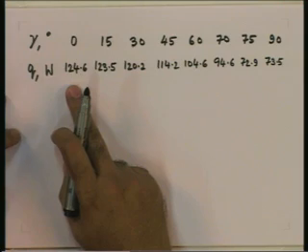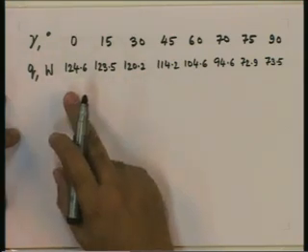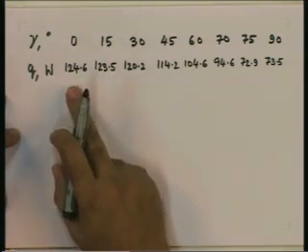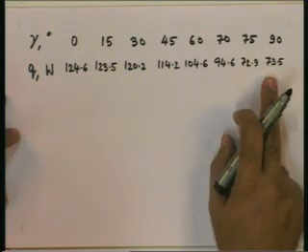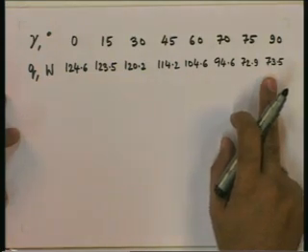So we get the highest heat loss when the cavity is horizontal, it reduces to about 72, 73 watts when it is 75 degrees, and increases slightly to 73.5 watts.